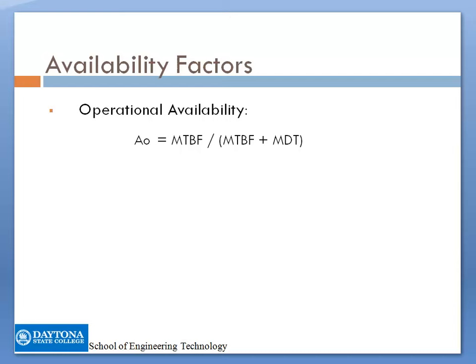So this is how maintainability takes place in the reliability in design as well. Remember that maintainability uses a number of different figures of merit, such as the mean time to repair, the mean time to service, repair hours per, let's say, 100,000 operating hours, preventive maintenance costs, and downtime probability.